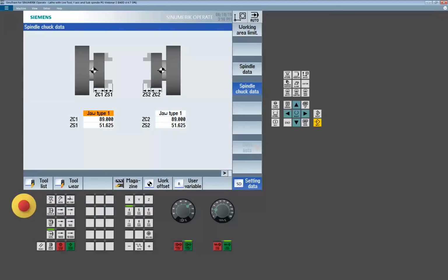I actually prefer, to be honest with you, using the G75 command instead of the SUPA command. The problem with SUPA, as a lot of us know, is that it suppresses the active work offset system, but it doesn't suppress the tool offset by default. There is actually a machine MD, Mike, you might not realize this, that you can change that behavior, but I would suggest not, because all of your machines are set up with it not suppressing the tool offset.